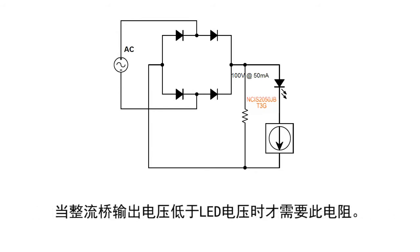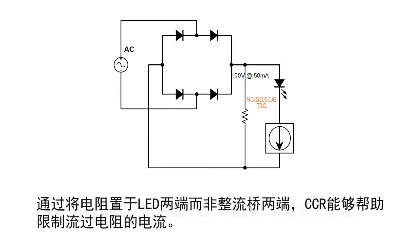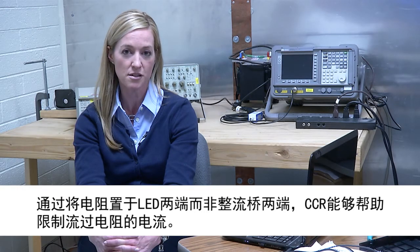The resistor is only needed when the voltage out of the bridge is below that of the LEDs. By placing the resistor across the LEDs compared to across the bridge, the CCR can help limit the current through the resistor. The current being controlled by the CCR would be shared by the LEDs and the resistor.